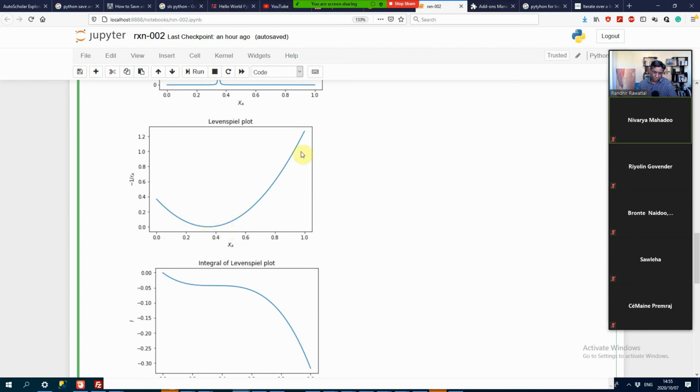And then you would add up. So we've already talked about how to estimate that area and hence the volume there. And then for the CSTR, we've shown how you just look up the RA value. In this case, it's 0. It doesn't make sense. You will end up with a 0 volume CSTR. But anyway, for more realistic kinetics, you'll get some finite value.